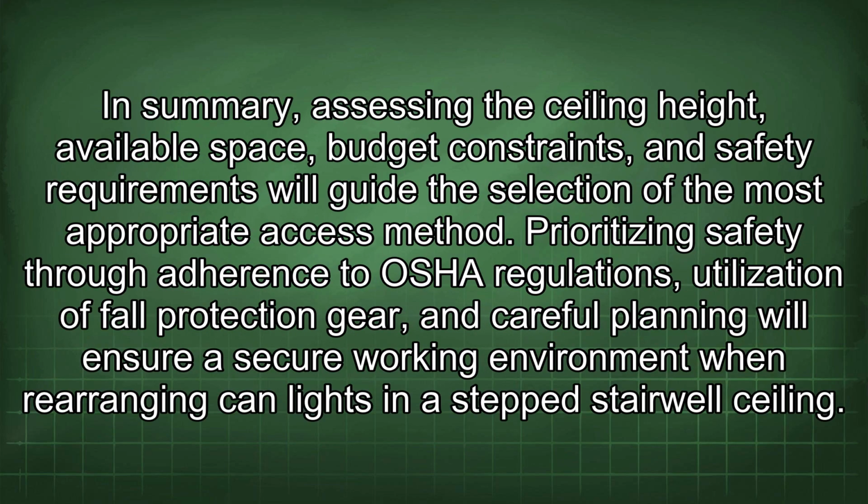In summary, assessing the ceiling height, available space, budget constraints, and safety requirements will guide the selection of the most appropriate access method. Prioritizing safety through adherence to OSHA regulations, utilization of fall protection gear, and careful planning will ensure a secure working environment when rearranging lights in a stepped stairwell ceiling.